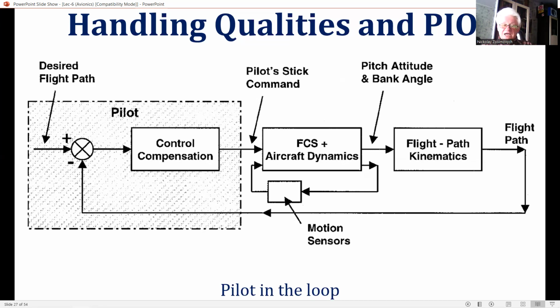Good handling qualities can be defined as those characteristics of the dynamic behavior of the aircraft which enable the pilot to exercise precise control with low pilot workload. The achievement of good handling characteristics is a major objective in the FCS design. The quality of the handling characteristics and the pilot workload are generally expressed in terms of the Cooper-Harper scale of rating from 1 to 10, 1 being excellent and 10 the worst qualities possible.